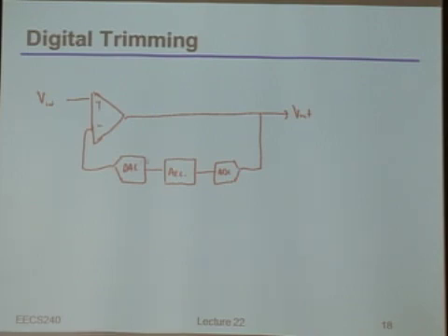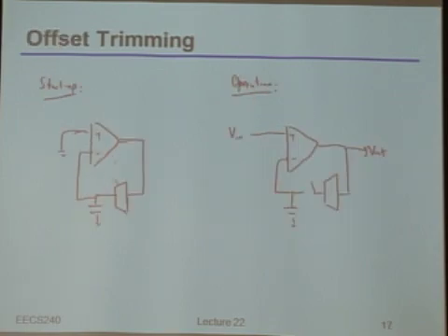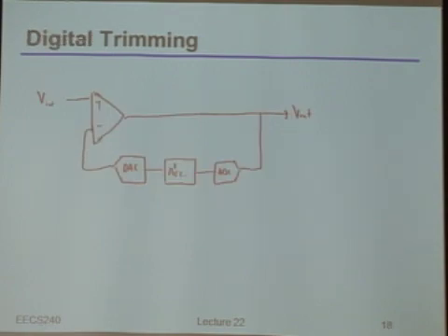No, so the idea here is that you would do this just once at the beginning. In other words, you would basically replace this OTA plus capacitor with this ADC, accumulator and DAC. You'd run it once at the beginning, and then when you're done, you basically turn off this ADC, meaning you essentially feed zero, quote-unquote, input to the accumulator, meaning you don't change that accumulator code anymore. You just have that drive the DAC, and then as long as the power supply is up and there isn't some weird random noise particles or whatever it is, the DAC will just keep its value constant.